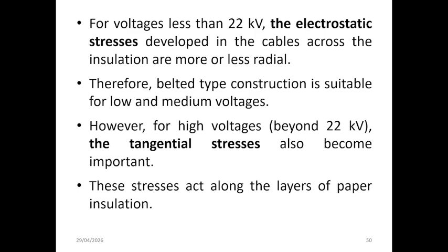However, at higher voltages above 22 kilovolt, tangential stress also becomes significant. This stress acts along the layers of paper insulation and can lead to insulation failure, which is why belted cables are not suitable for high voltage applications.